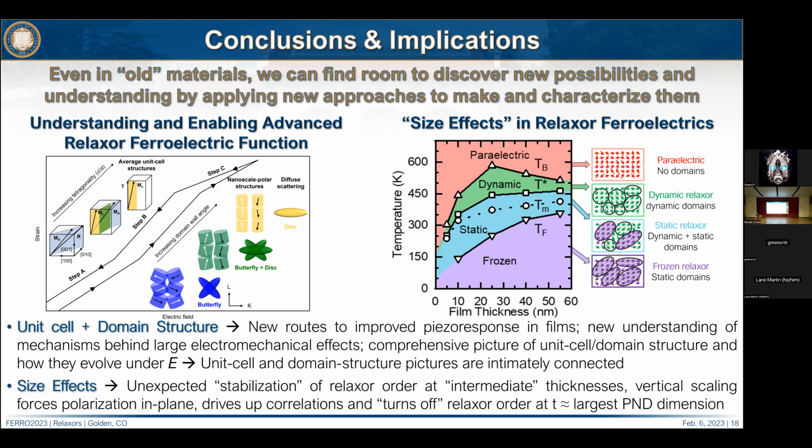What we're doing is taking it one step further. We're actually creating artificial superlattices out of these kinds of materials where we specifically order them along different directions at a few unit cell length scales, as kind of the ultimate manifestation of what you're saying. And what you get is crazy anisotropic properties. You'll get relaxor behavior in one direction and something that looks ferroelectric, or in some cases dielectric, in the other direction. So that is a very interesting design approach that I think is quite productive.